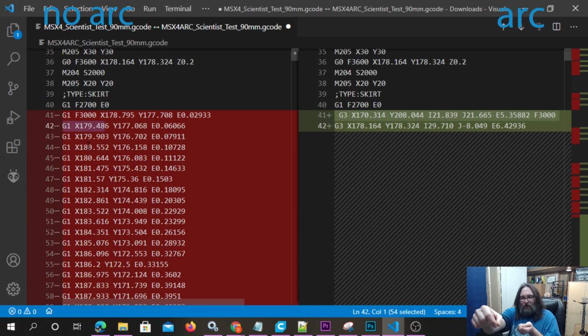So that creates that straight line motion back and forth. Now it can be diagonal, right? But it's always a linear move. So it's a straight line. Where the G commands, so the G3, they're a little tiny bit different than the linear motion. So the G3 still gives an X and a Y coordinate, and those still mean the same things.